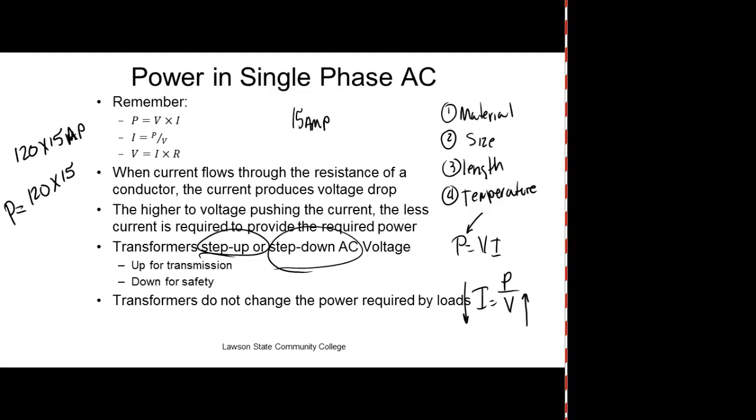We don't have 440 in this building. The only thing we got in this building is 220. That robot right there, this ABB robot, is 440, and the big FANUC over there runs off 440. So what did we have to do to get 440? We have a step-up transformer. You can't see the one for the big FANUC. It's in a mechanical room upstairs. But the one for the ABB is on the floor over there. It's a 15 kVA transformer.